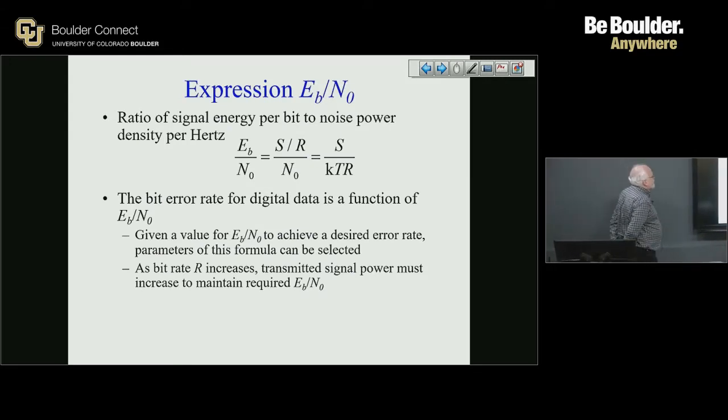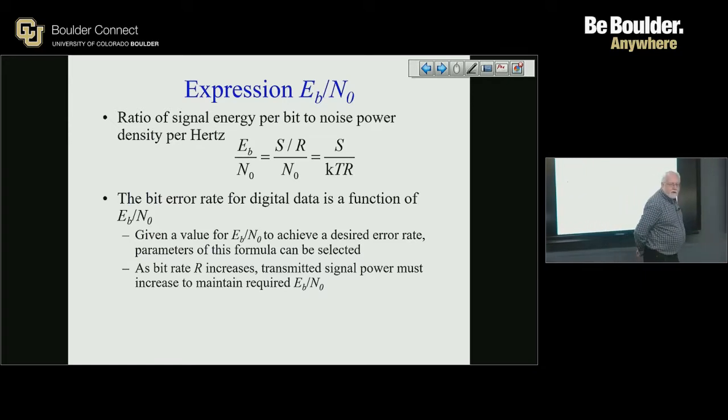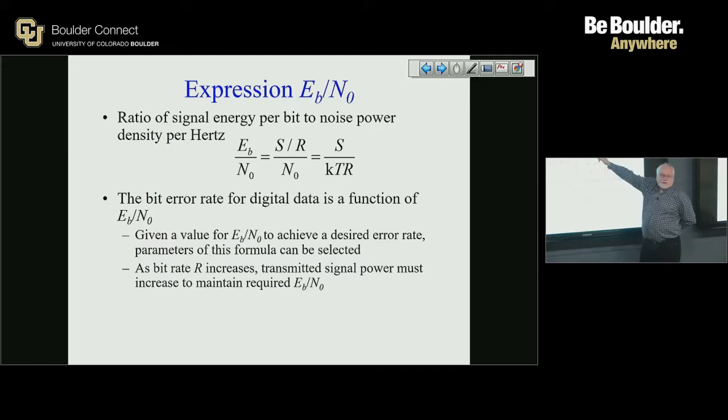The other thing here is we need to start working our way towards talking about bit error rates and packet errors. So there's this thing called Eb over N0, or EbNo, as people call it. It's the ratio of the energy per bit divided by the background noise. This could be man-made noise, but the best you can do theoretically is KTB. EbNo is also called the signal noise ratio, the ratio of signal power to the noise power.